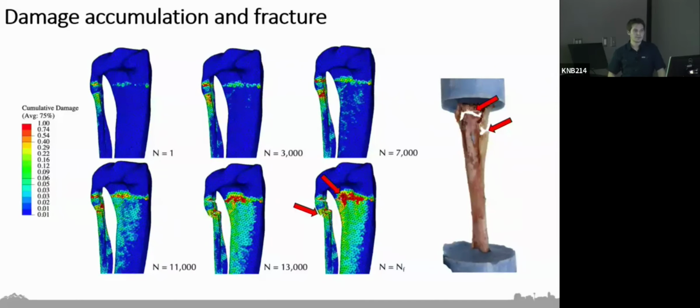Would there be some benefit to weighting them? Because if I just look at this here, I would get the sense that if you're a little bit wrong, and I think it was E5 or E6 that was at the top here, if your modulus was out by a little bit there, you probably have a lot of error. But if your modulus is out down the distal end of the tibia, you're probably fine. So is there some benefit to that? It's a good point. I don't know though. I wouldn't know how to weight them, because I don't have an idea of whether or not that material is actually off. So I don't think I'd be able to determine weightings. You could potentially optimize it at the same time.